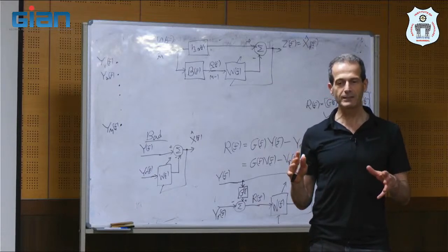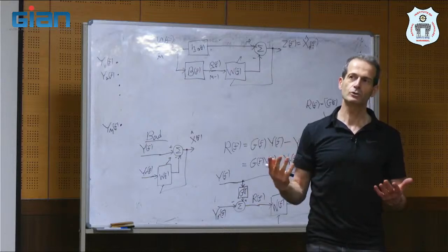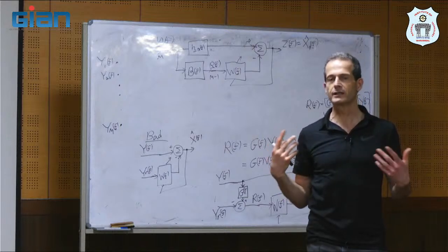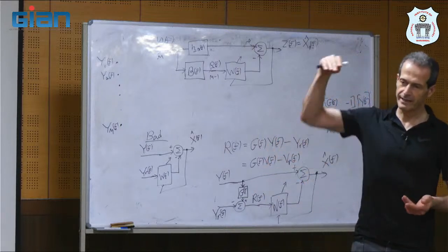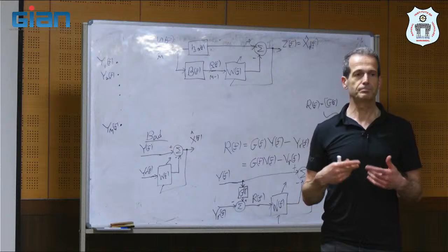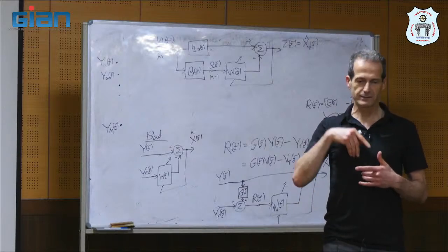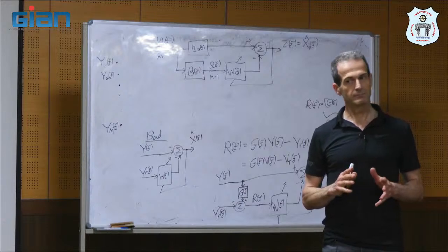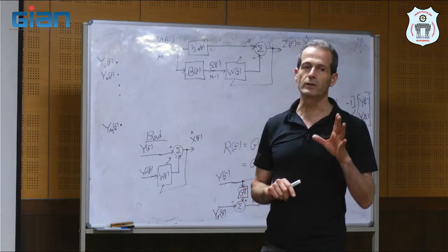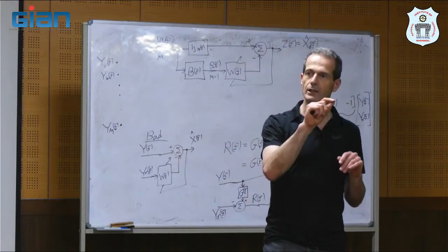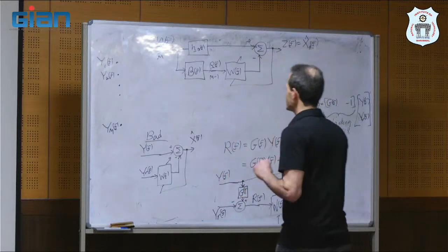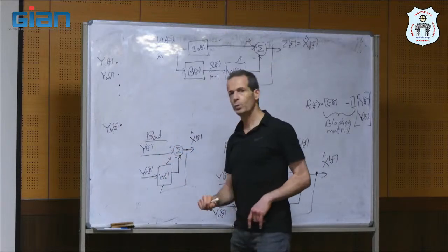Most babies, the head is down. So you want to put the microphone close to the heart, which is somewhere in between the shoulders. If the head is down, you will put it down. But if the head is up, probably you need to put it in a higher place, at the top of the abdomen. Okay? So you need to try where the pulse, the heart rate, will be strong. You need to put the sensor, the main channel, where you can get the strongest desired signal.